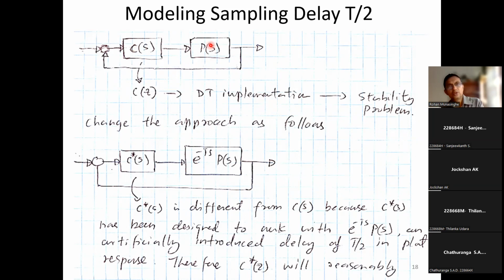Now with the zero-order hold and all, P(s) is going to change into something. Therefore, your controller has to be designed based on that model, the equivalent discrete model. And you get the point, right? Therefore, my initial advice to you was to go ahead and design your continuous time controller with all the tools in continuous time, and then transform the continuous time controller into discrete time. It's not very accurate. Now you know that. Okay. So this is the process.